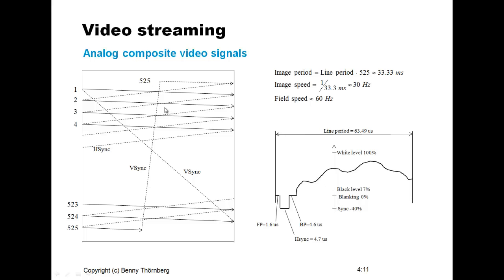And an interlaced scan mode was used, which means that lines are progressed interlaced with the odd field first, and then after this comes the even field. So all the odd lines were sensed first until the end of the last odd line, and then there will be a transfer from the end of the photosensitive area to the beginning of the photosensitive area.